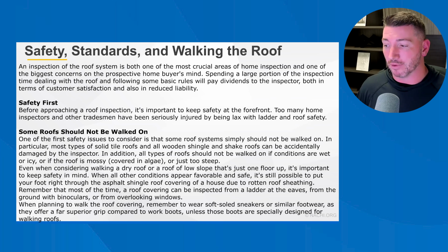Remember that most of the time, a roof covering can be inspected from a ladder at the eaves, from the ground with binoculars, from overlooking windows, or currently drones. When planning to walk on a roof covering, remember to wear soft-soled sneakers or similar footwear, as they may offer far superior grip compared to work boots, unless those boots are specially designed for walking roofs. Those boots are called cougar paws. If you don't already know what they are, I would encourage you to get a pair.